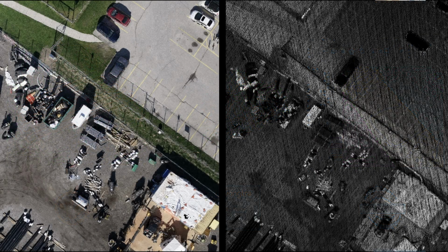Once we have the data, here's a direct comparison between the photogrammetry version of it and the LiDAR point cloud, right? So with photogrammetry, it's pictures. So we have color, we have pixels, and we can create a point cloud at almost infinite density. We can really just choose whatever density we want to extract those points from the pictures.